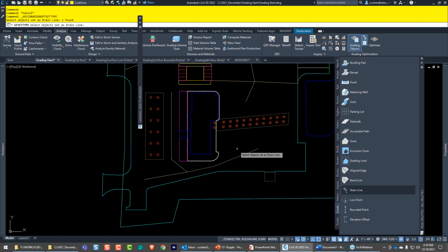The key thing I would recommend you do is organize, just like anything in CAD, organize your objects by layer, etc. One of the other things, I did see a great Autodesk University presentation. I would look it up. I can't remember who was the presenter, but what they did, they actually created a bunch of hatching, and they applied that hatching to all the objects that were closed, right?